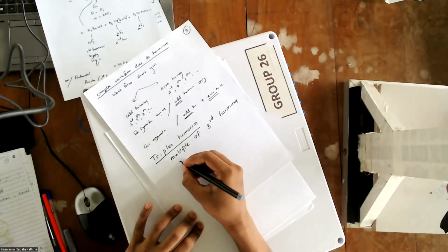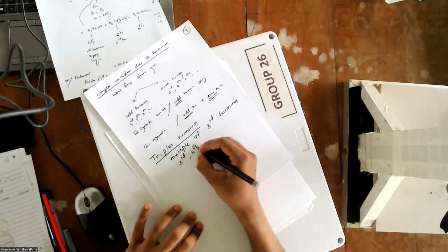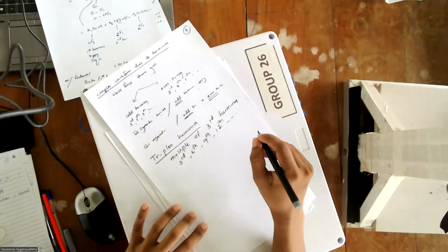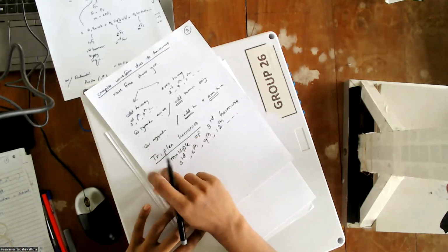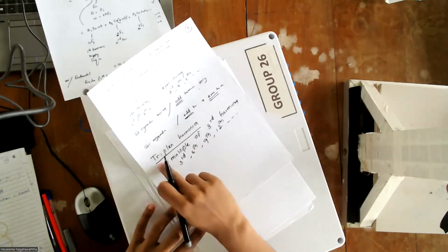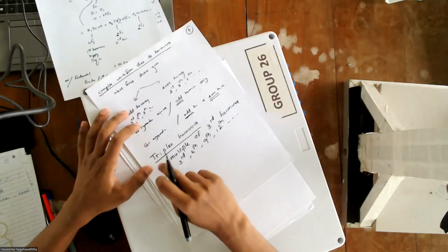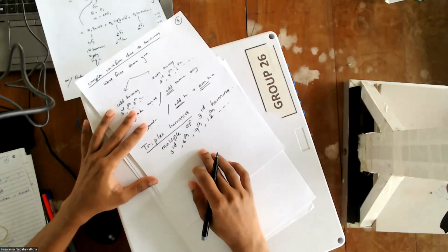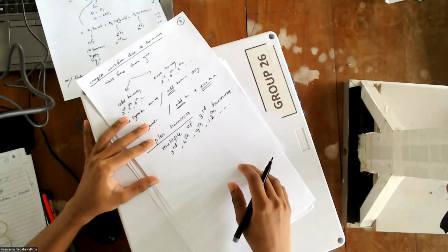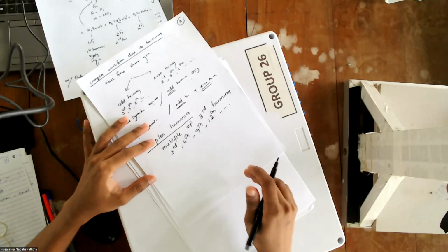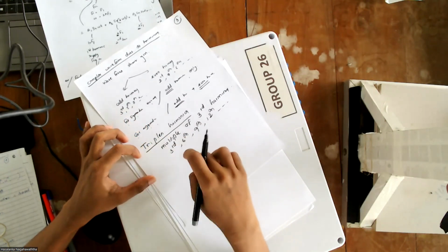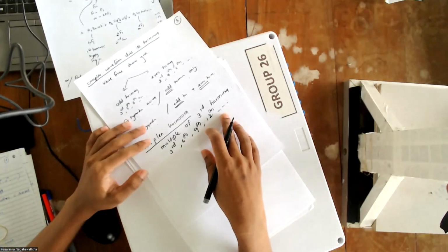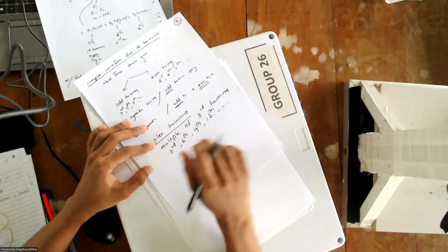Multiple of third harmonic means third harmonic, sixth harmonic, ninth harmonic, 12th harmonic, likewise. In power electronics, you may hear these triple-n harmonics, and memorize them. Due to these harmonics, the output waveform is distorted, and this effect is called harmonic distortion. I showed you using the Proteus file.